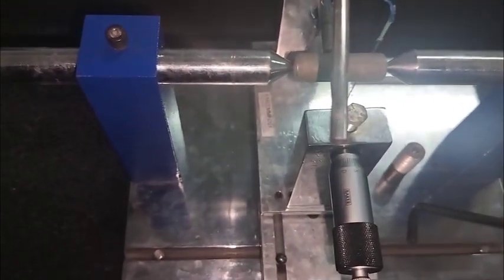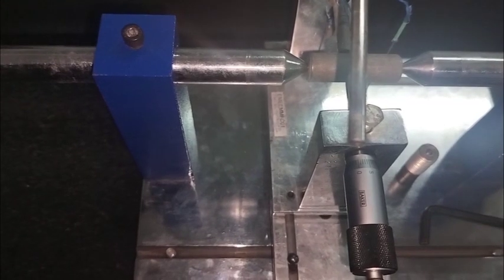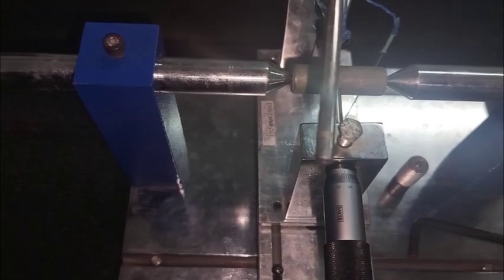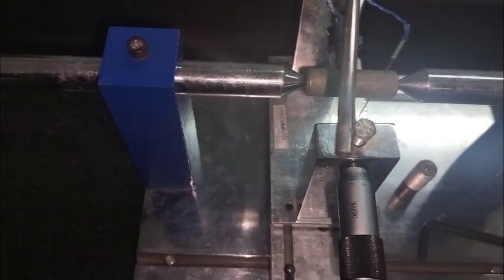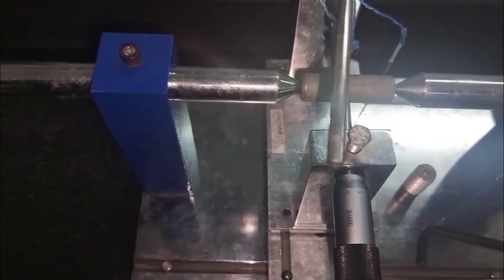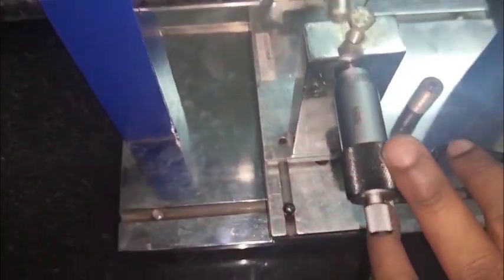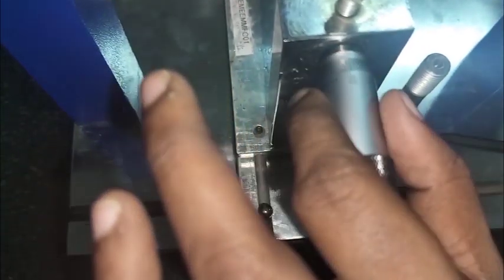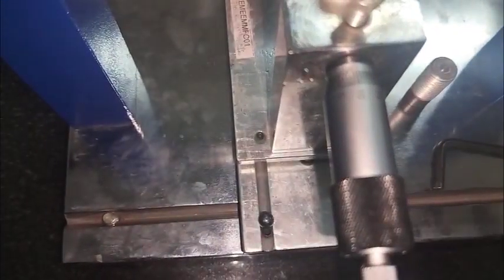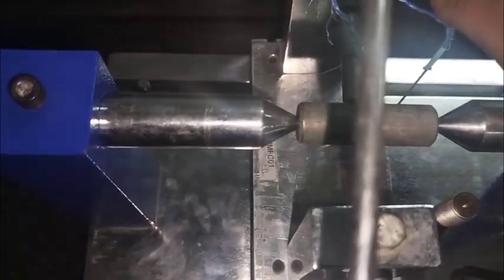Then the description. The floating carriage micrometer is a micrometer used to measure the major diameter, minor diameter and effective diameter of a threaded surface. This micrometer has a main scale and a thimble scale with an anvil attachment, and a pressure gauge is also attached for applying the pressure in between. There is a dial gauge. The least count of the floating carriage micrometer is 0.002 mm.